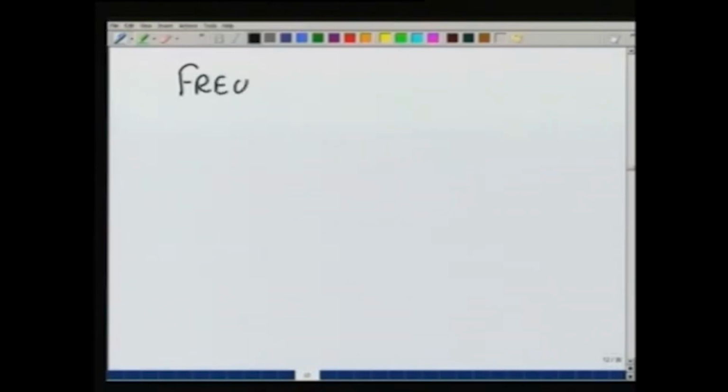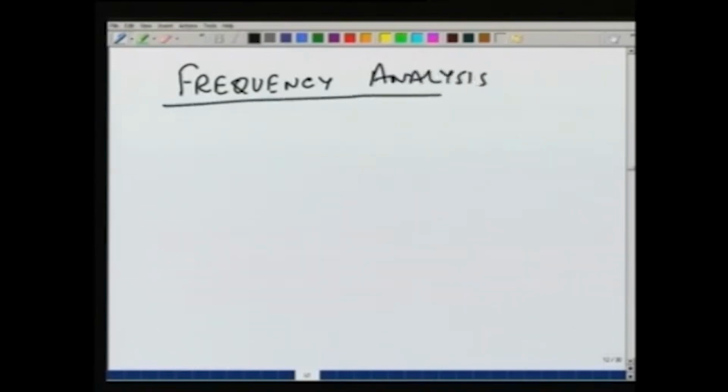The other analysis which we can do from the rainfall data is based on statistics and is called frequency analysis. So, not only are we interested in finding out how much rainfall occurs, what is the maximum value, but we should also be able to tell that within, let us say, a period of 10 years or 50 years or 100 years, what is the maximum value of rain which we can expect, and based on the importance of the project we can choose what is known as the return period.